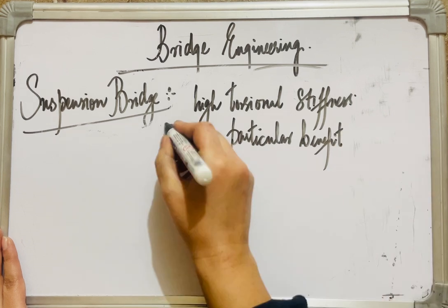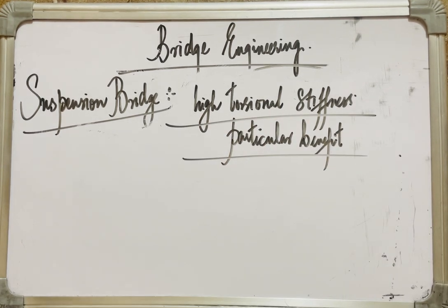All right, so a box girder is essentially a girder in the shape of a hollow box, and I told you that the deck in case of a suspension bridge consists of a stiffened steel plate or ribs or troughs and floor beams, and the deck can be made of strong steel trusses or of a streamlined box girder. And the box girder is used for bridges in those situations where we have to create longer spans because the self weight of the bridge needs to be minimized, and where we have to resist the torsion oscillations, because these girders have the excellent ability of high torsional stiffness, and this can be of great value in case of a suspension bridge, how we'll come to know.